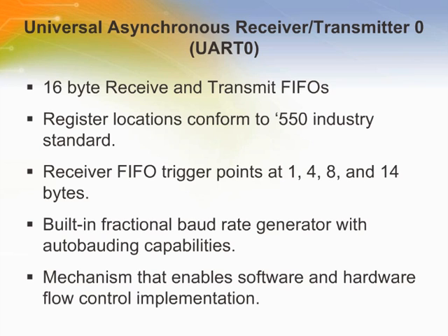The UART0 TX shift register, U0TSR, reads the data stored in the U0THR and assembles the data to transmit via the serial output pin TXD0. The UART0 baud rate generator block, U0BRG, generates the timing enables used by the UART0 TX block. The U0BRG clock input source is the VPB clock, PCLK. The main clock is divided down per the divisor specified in the U0DLL and U0DLM registers. This divided down clock is a 16 times over sample clock,